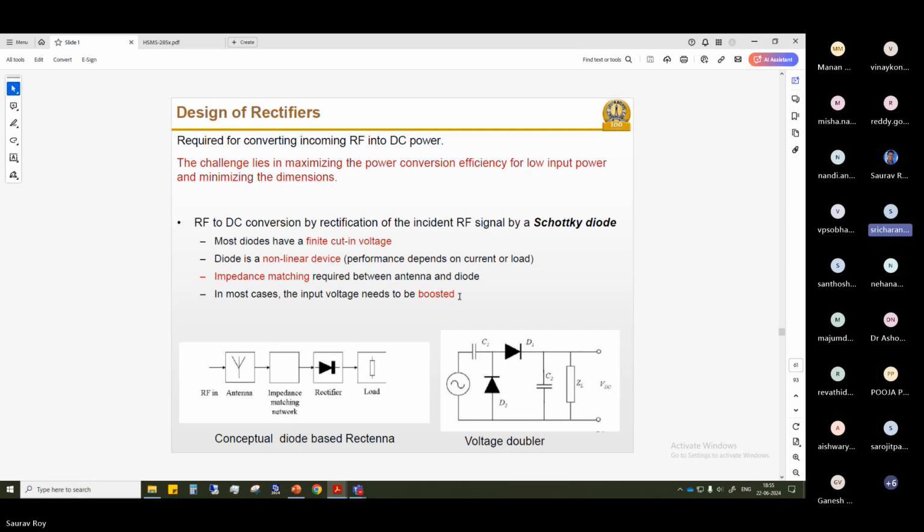Maybe the capacitance at the junction of the diode. No, it does not have anything to do with capacitance. I am saying, generally in your normal rectifier circuits, you have some 5 to 10 volt AC coming out, and then you get some DC because of the half wave or full wave rectifier. Here, what do you get? It's very little voltage, let's say in millivolts or microvolts at the input end. So do you think normal diodes will work here? Why is a Schottky diode required?